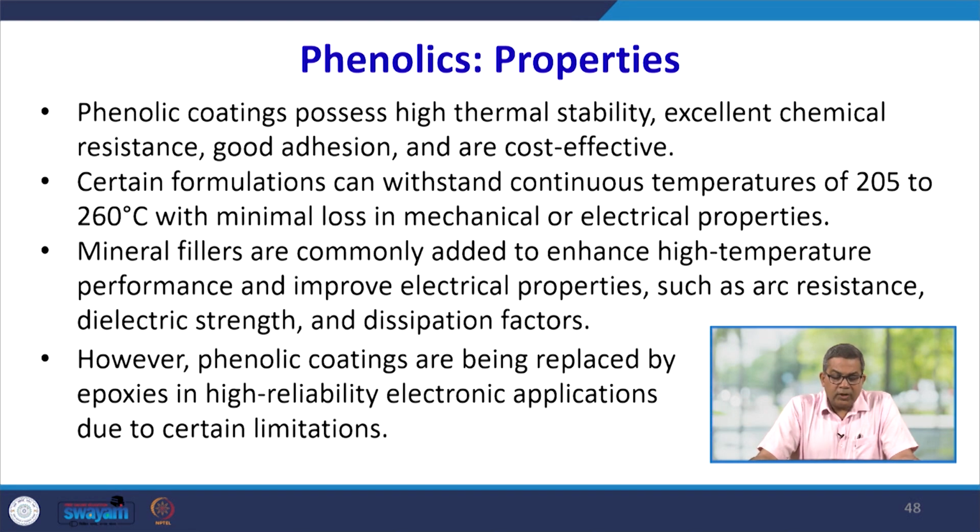Now, these phenolic coatings possess high thermal stability, excellent chemical resistance and good adhesion, and they are cost effective. Certain formulations can withstand continuous use at a temperature of say 205 to 260 degrees Celsius with a minimum loss in mechanical or electrical properties. So, mineral fillers are commonly added to enhance the high temperature performance and improve the electrical properties like arc resistance, dielectric strength and dissipation factors.